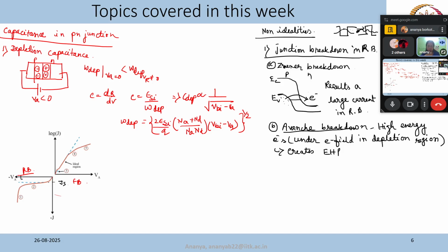This voltage is known as the breakdown voltage, and if you check the data sheet of a diode, you will find this. We don't want to operate our diodes near the breakdown or even above the breakdown voltage, if we want ideal rectifying behavior of a diode. So